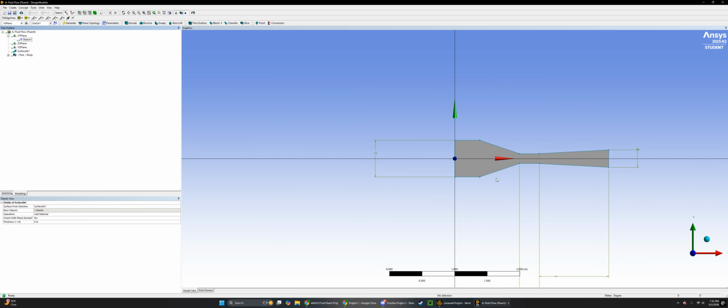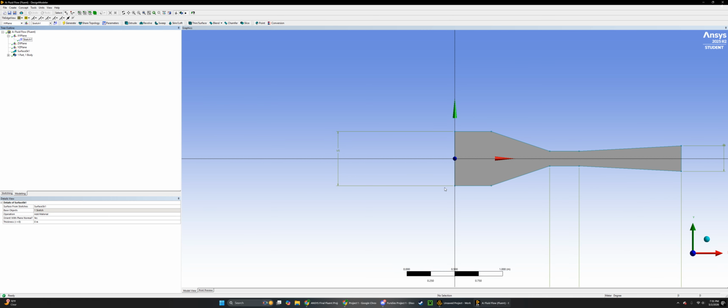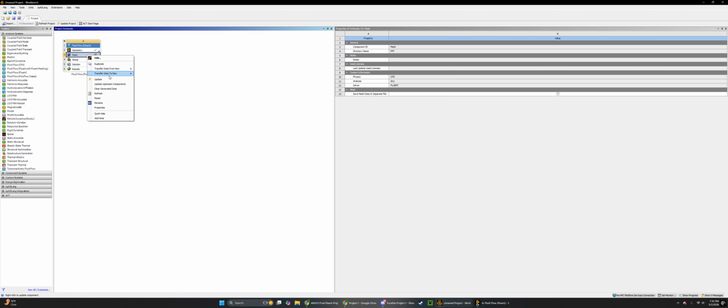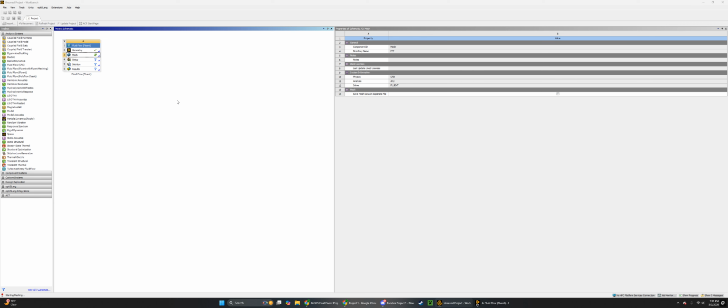And then we're going to draw a construction point on the origin. Then constraints, midpoint the line with this. Perfect. So right in the center. Can zoom a little more. Alright. Next step.